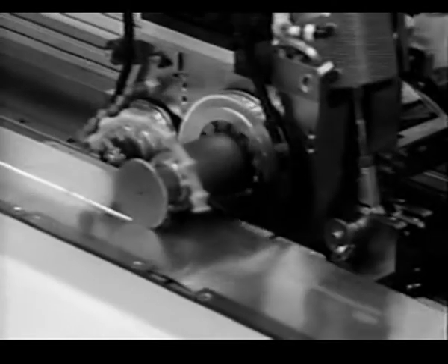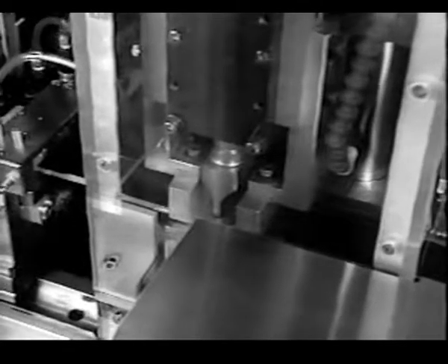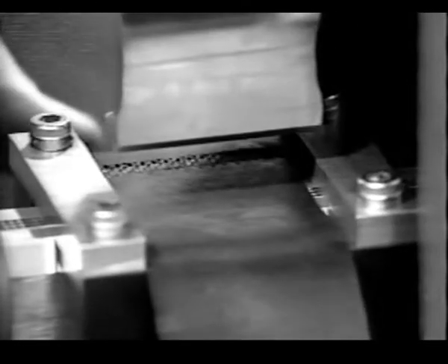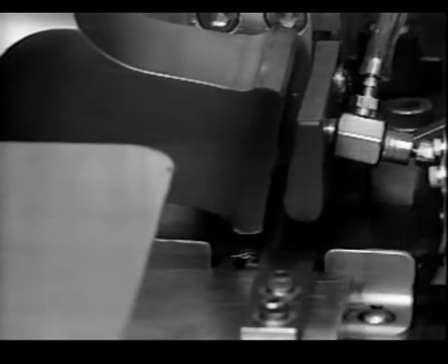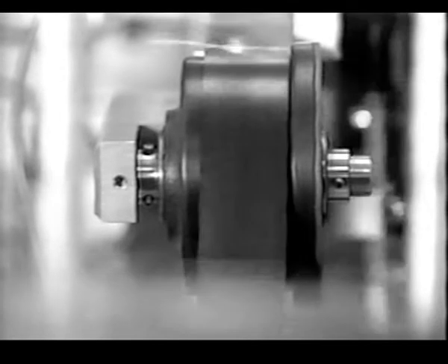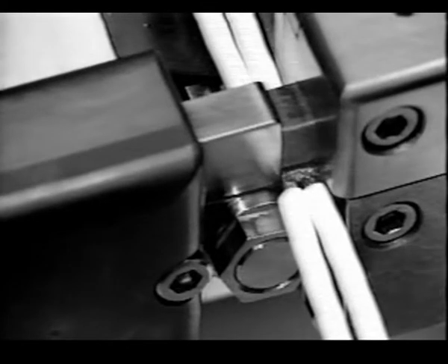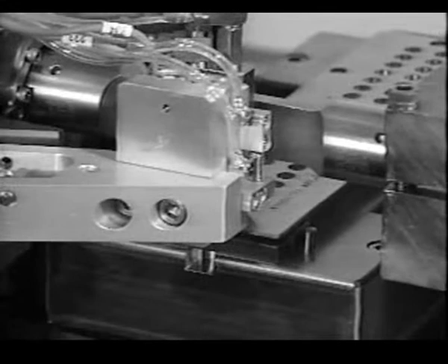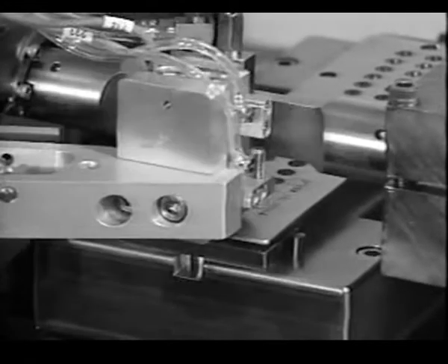Workpiece distortion is limited. Ductile metals in similar or dissimilar combinations are ideal workpieces, although hard metals also can be welded. Filler metals are not normally required, although they can assist in joining difficult-to-weld dissimilar metals. The electrical and electronics industries are the principal users of ultrasonic welding. Limited applications are also found in the automobile, nuclear, and aerospace industries.